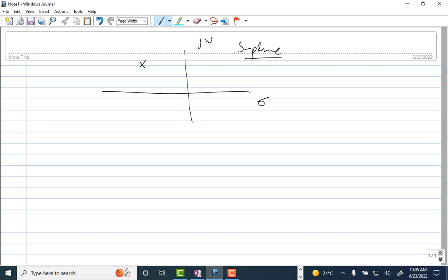For example, if I have a pole or any point here, and I drop down, this distance, if I represent it by sigma d, makes this point minus sigma d. This minus sigma d is normally equal to, in second order, zeta omega n.